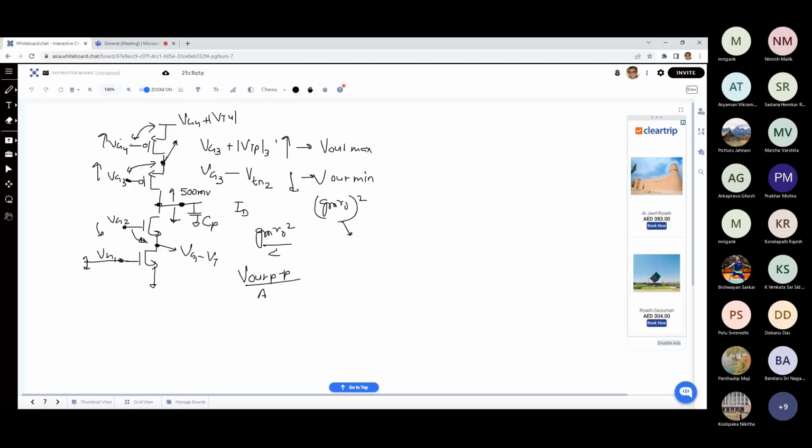Now, in certain cases, when we use amplifiers in feedback configuration, like we have seen, we want to use amplifiers as voltage followers, where the output signal is equal to the input signal, and we need to handle large swing at the input also. And we want a very accurate voltage follower, so we want to maintain good accuracy and at the same time have large signal swing. In that case, this kind of amplifier will give a challenge, right? You can't apply a large input signal swing, and you also need to maintain accuracy, so you can't sacrifice the gain.